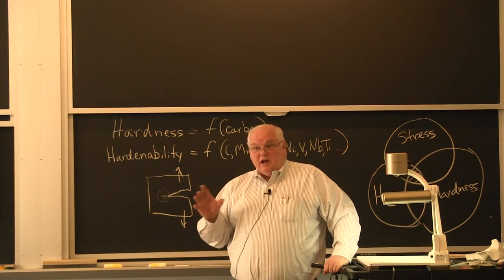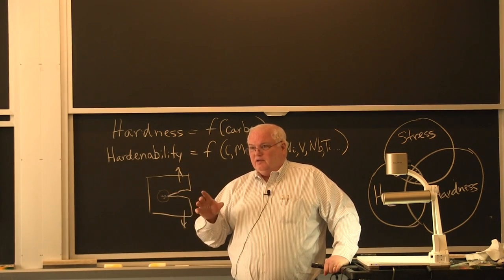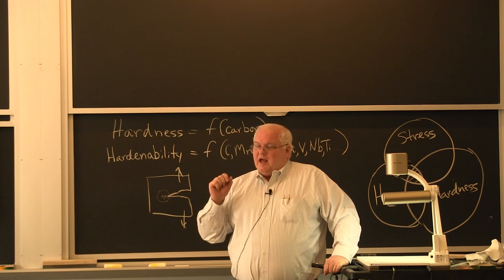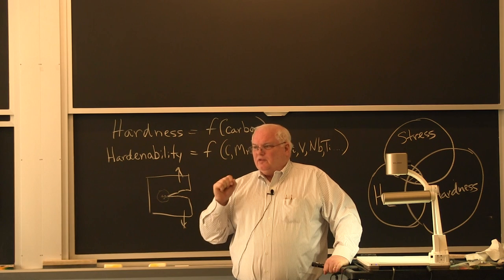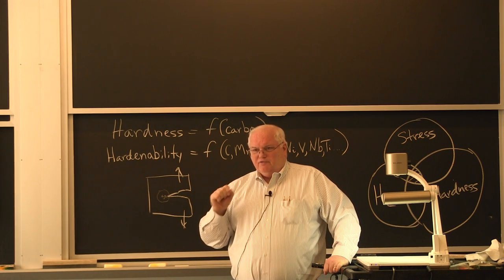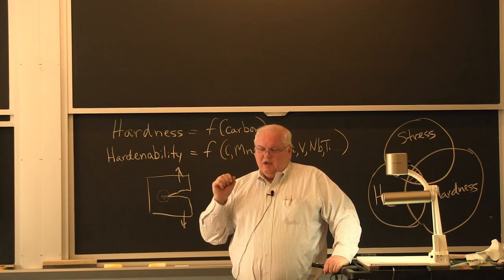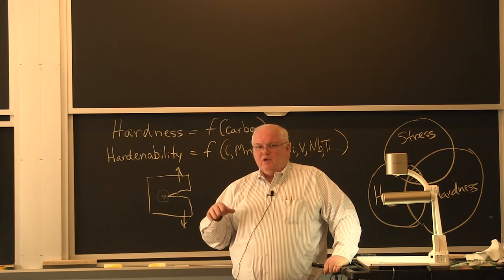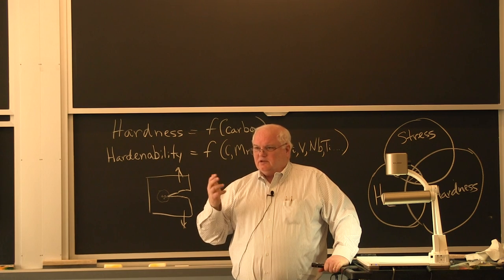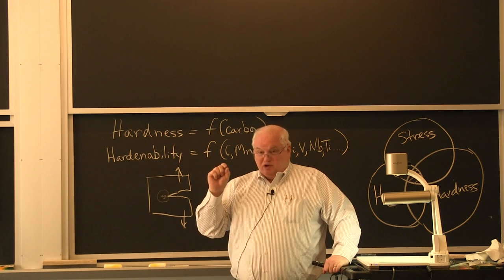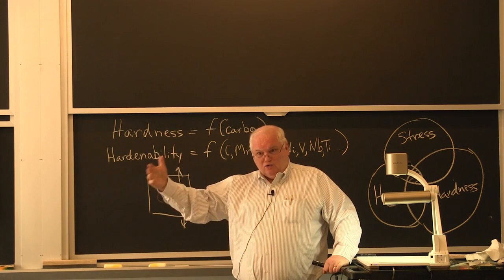And that's why, when I electroplate, we talked about electroplating of bicycle tubes, if they had plated the bicycle tube and gotten it into a 375 degree Fahrenheit furnace, which is the standard temperature, within an hour, they wouldn't have formed a crack. And the bicyclist wouldn't have become a paraplegic. You formed a crack, and a fatigue crack grew from that.